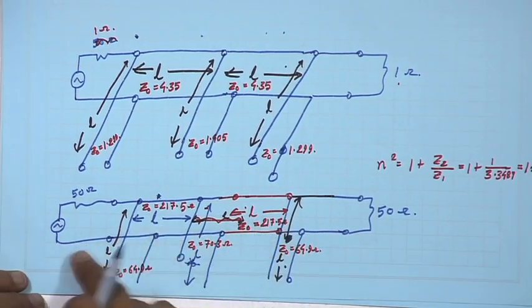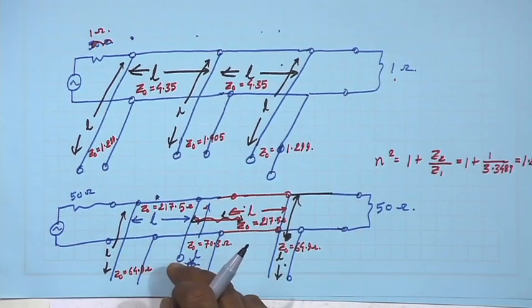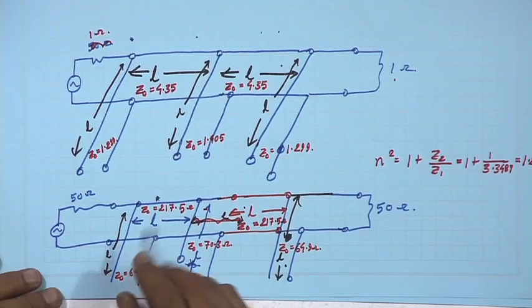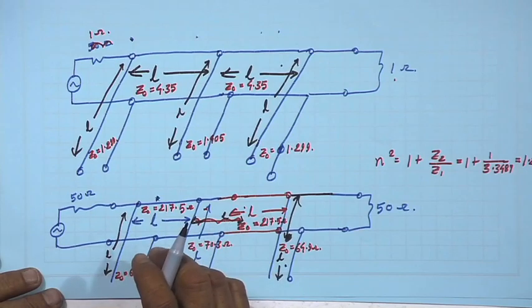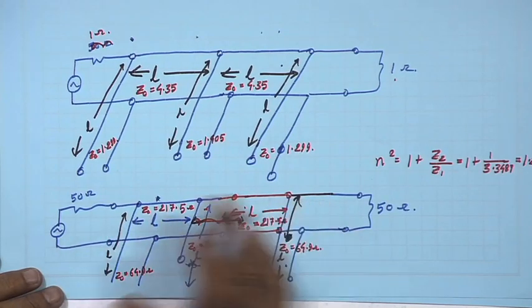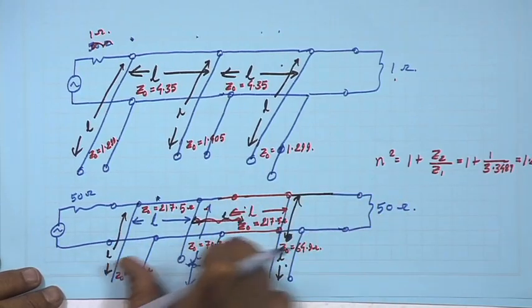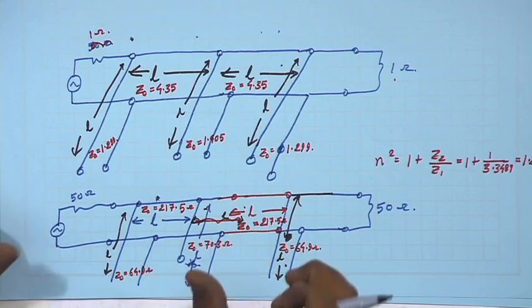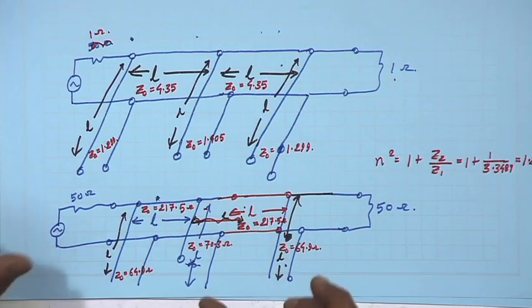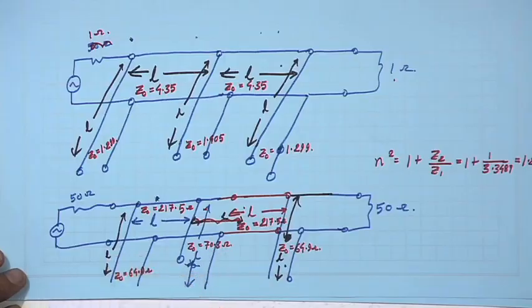Their impedances on both sides are matched to 1, that is why they do not disturb the operation of the filter, but what they do is separate the 2 stub elements, so there is enough separation between them. So that at any discontinuity, any higher evanescent modes that get generated can be tackled there, particularly at higher microwave frequencies.